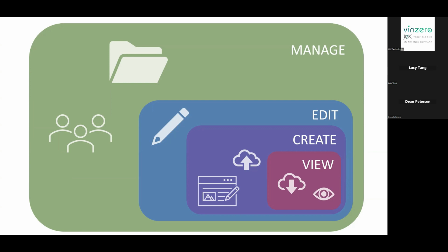We're very familiar with this one as we've been looking at BIM Collaborate Pro, mostly through the eyes of a project admin. The manage permission allows you to view the entire folder structure, view, download, upload, and edit files, as well as publishing markups. It's also a given that if you have the manage permission, you are given full administrative rights. So this can be assigned to members that are not project admins. By default, account and project admins do get this permission on their own.